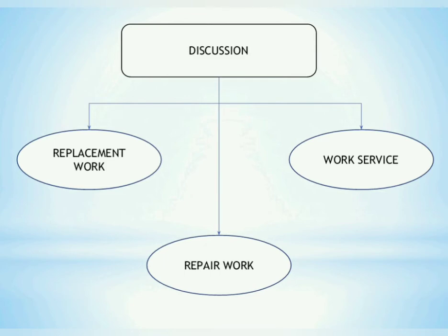Scheduled inspections should be done continuously for each recorded item to identify failures and damage. Replacement can prevent adverse effects on the performance and functioning of the building. Among the items that must be observed are the structural, mechanical system, electrical and water system, which are the main lifelines of buildings.